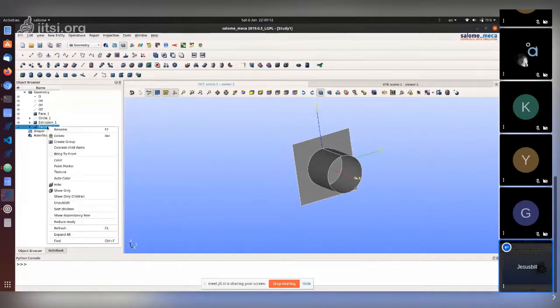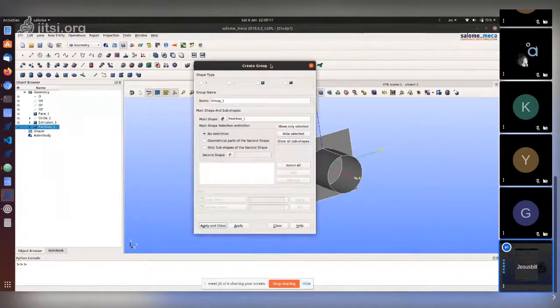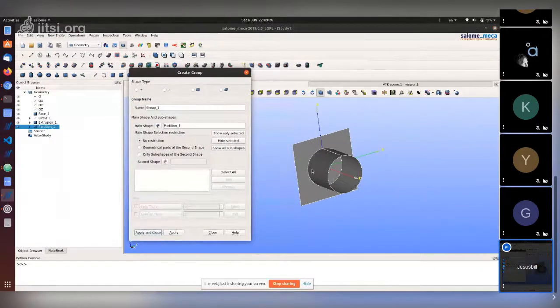And then the important thing, you have to start creating the groups. The group names are the ones that are going to give you the reference for the geometries that you're going to use for the command file then that you're going to create to do the analysis. And so here you can select the type of geometries. I'm going to select the faces. Let's say that I select all the faces, add. And I just select a name, let's say faces.